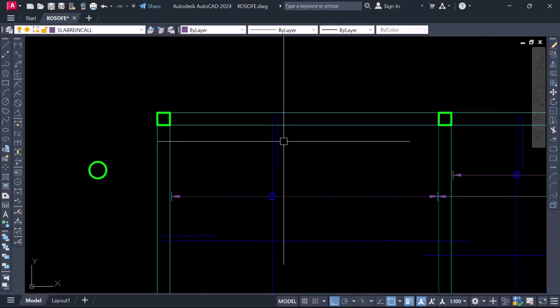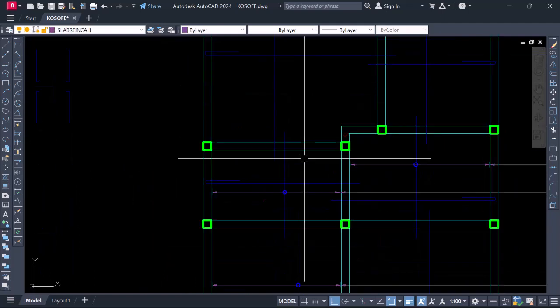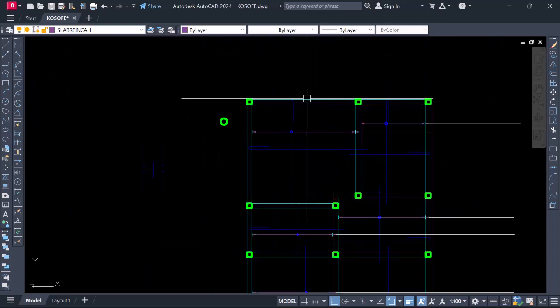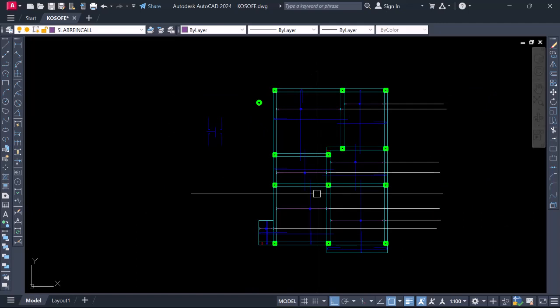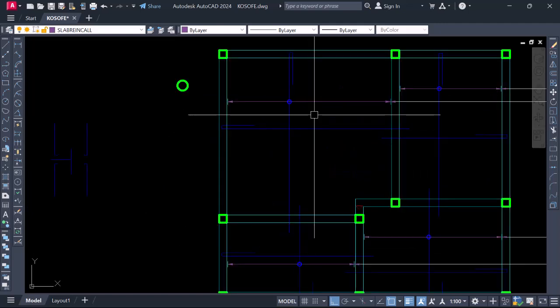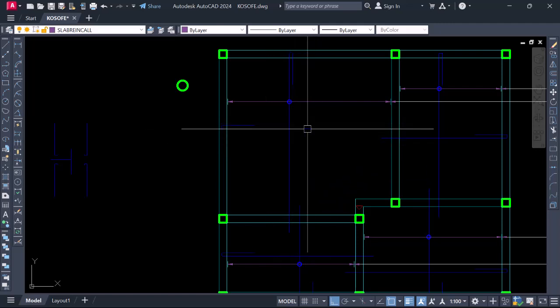Like you have your return, you have this top bar along this area. So we're going to create a top bar along the middle span, because the beam moment is going to act at all the supports. So we have the sag moment along the middle support, and when you have the sag moment at the middle support, you provide a reinforcement at the middle support.